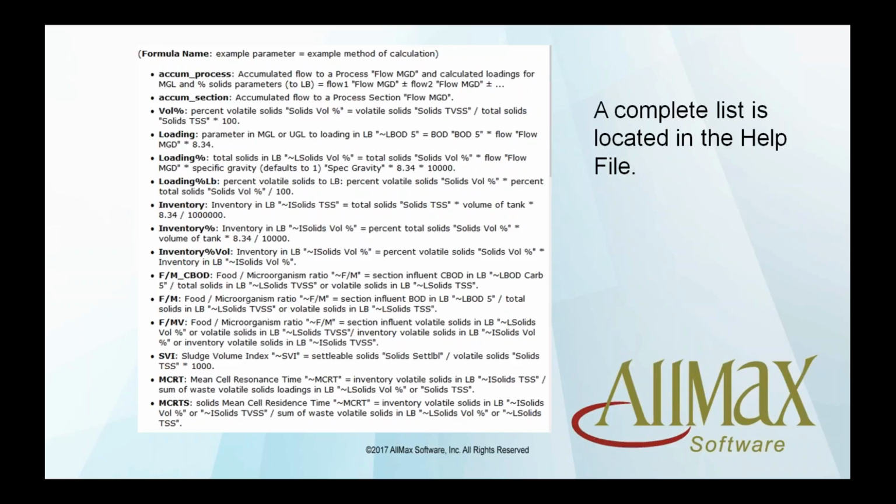We can also, going through a process setup, because of how we do it, attach chemicals to a given process. So in a water plant, say you want to track your dosage and everything, and you want the program to calculate that information. By defining the chemicals at a given process, we would then be able to give you values such as what the dose rate is, what the milligrams per liter feed is, and the pounds applied. We can also then give you a cost, because we could actually assign a cost to that. So say your chlorine is $1 a pound. Well, we can give you a total cost of what that would be, again, based off of the process setup.